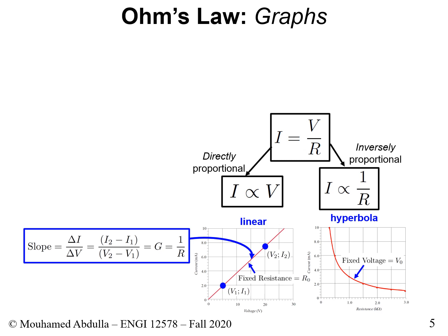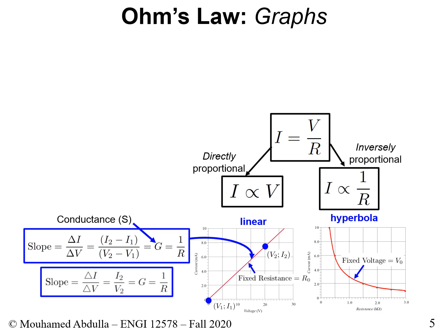Now, notice that, as we said before, 0, 0 is always one of the points on the plot. So instead of putting one of the points anywhere, we could in fact choose 0, 0 as the second point. It would make our analysis much easier. So let's just remove it from here, and let's just put it here. And if you put 0 for I1 and 0 for V1, your equation for the slopes simplifies to simply this.